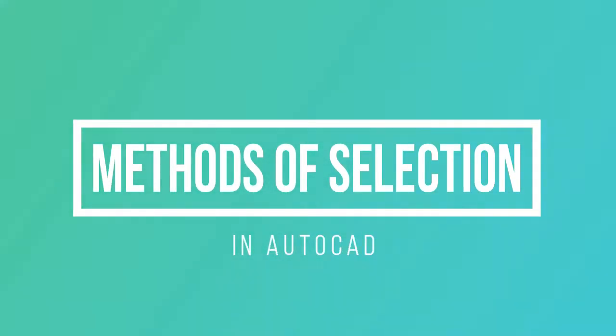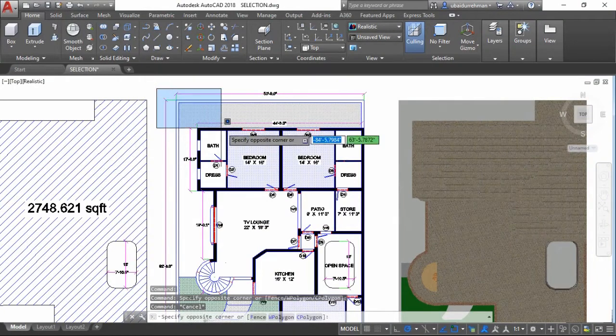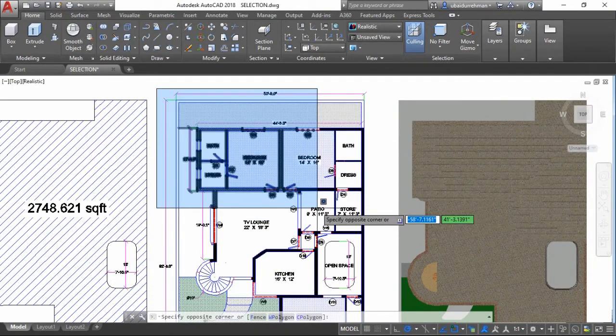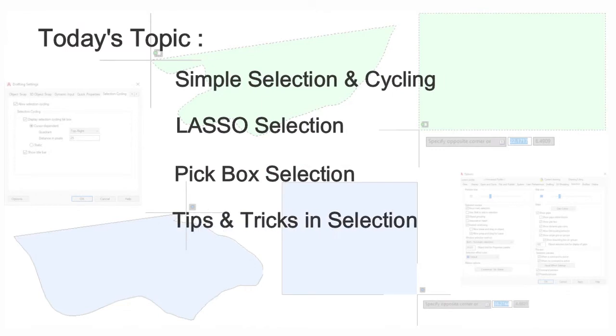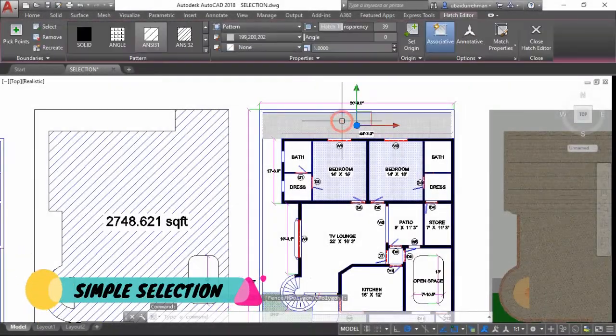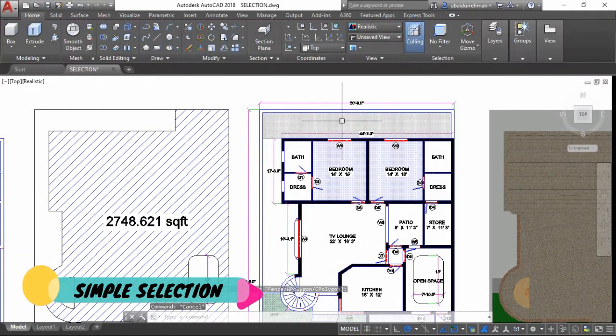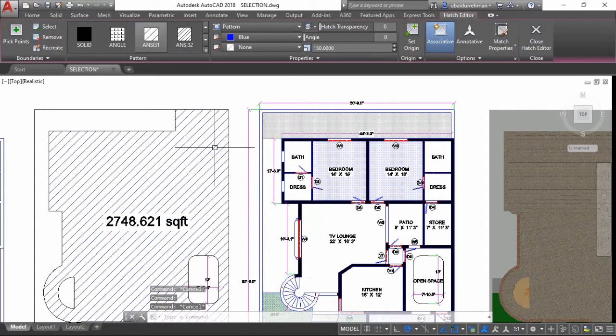Before you will be able to succeed in making manipulation in an AutoCAD model, you have to master the process of selection. And this is not unique to AutoCAD, in any graphics program selection is the key skill you have to master. There are lots of ways that you can select objects in AutoCAD. The first clue you have to the methods of selection is single left click. If you hover the crosshair on the object, it highlights, and with a single left click you can select it,